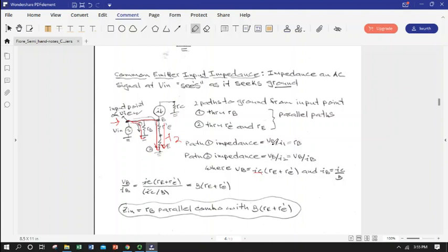We can use V sub B using this definition, and then use our two different versions of I. And in this case, we're going to define things in terms of just I sub B or I sub C and cancel out. So we can go through some math and put these two paths in parallel and end up with this expression.